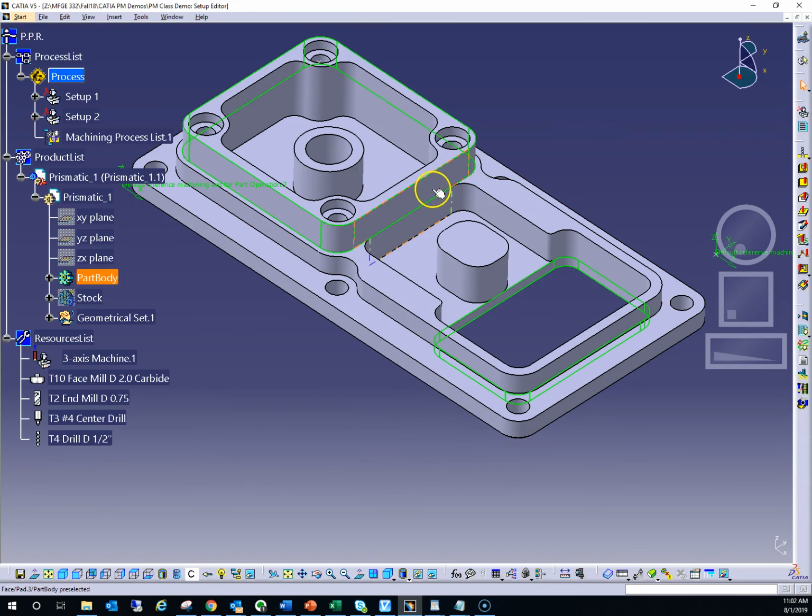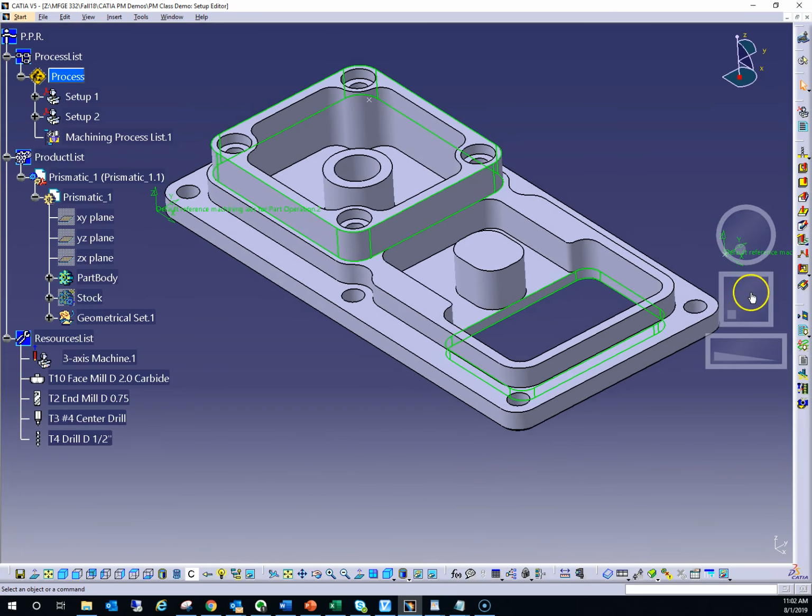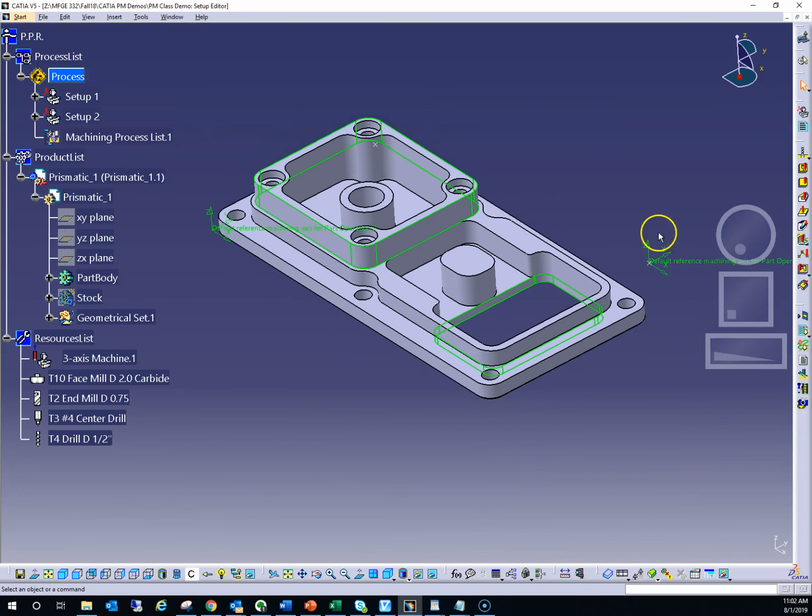So again, the cutter would run around. Notice that this wall here is aligned with the wall of the pocket, but we're really trying to machine this step or ridge that runs all the way around. So again, that's kind of the process that one goes through in terms of trying to come up with a plan to machine this.